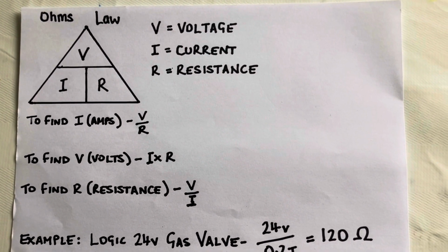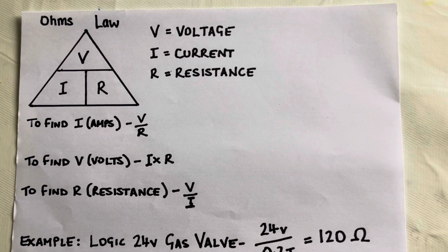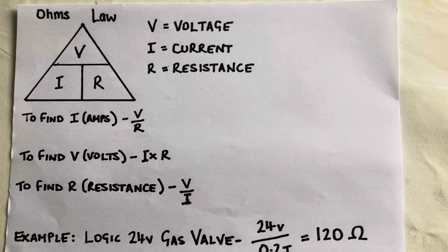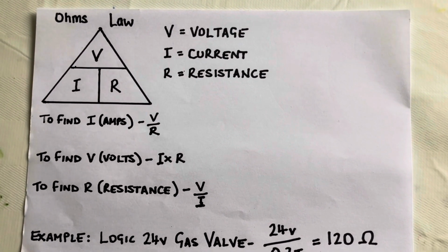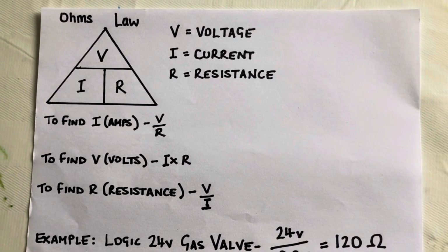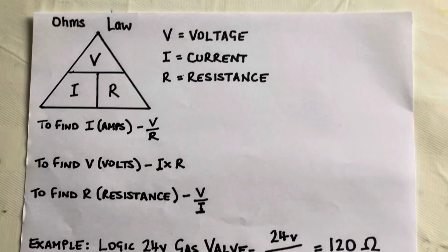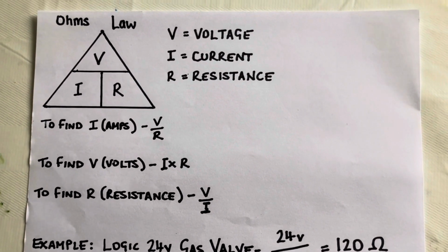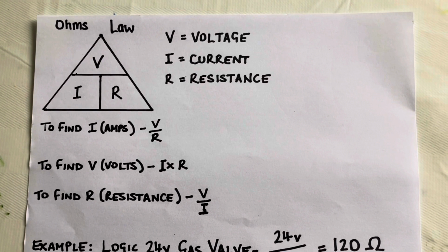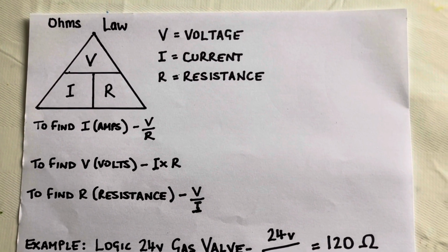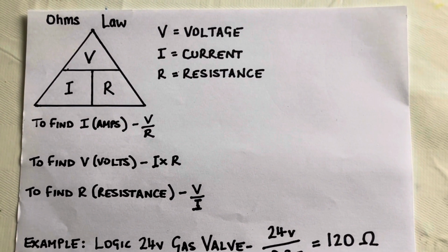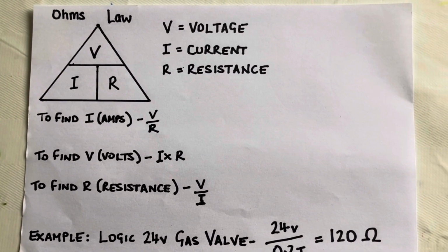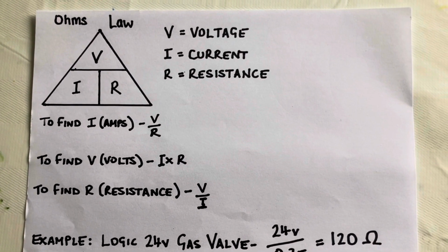Because a lot of people, when they repair boilers, they go for parts. Let's say you've got a fault with a pump and you're not getting power to the pump. People immediately assume it's the circuit board without even testing the harness. I've seen it so many times before. So I just want to show you how to do some electrical checks. Mainly they're going to be dead tests. We're not going to be doing much live testing today. We're going to be doing resistance testing and continuity testing.